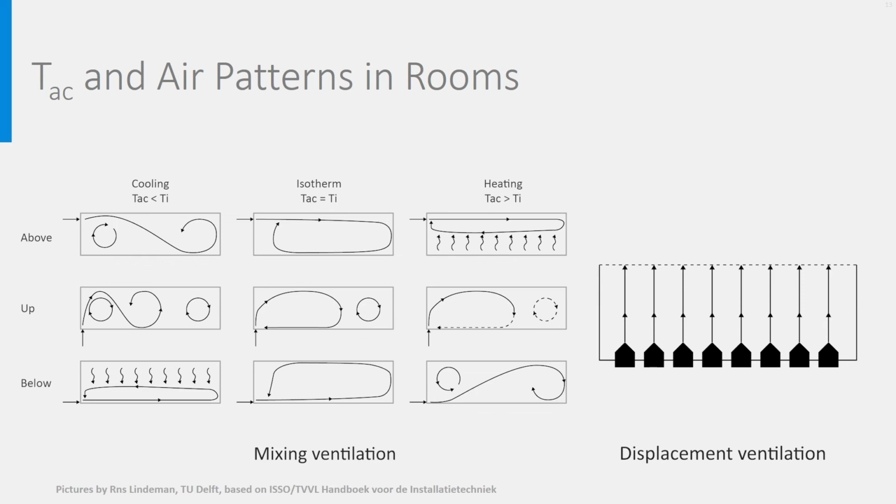Typically, this will be used in rooms where spread of pollutants should be avoided, like clean rooms, operation rooms in hospitals, theaters in which the valves are placed in the chair itself. The direction of the flow depends on which way one wants to transport the pollutants and also on the expectation of the system being used essentially for cooling, that will be then from down under, or essentially for heating from below to above, or just for ventilation.